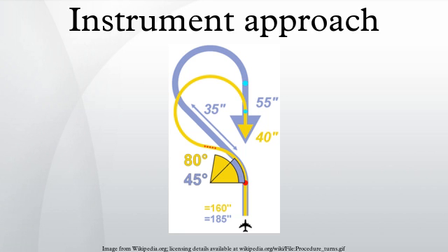Most instrument approaches allow for landing in conditions of low visibility. See Airport Requirements section. There are air traffic control considerations with low visibility approaches. There must be longer gaps between aircraft on final approach both to protect the ILS signal and to cope with slower runway vacating times. Concepts in detail.